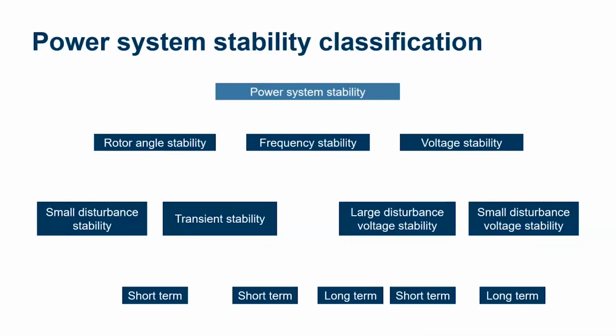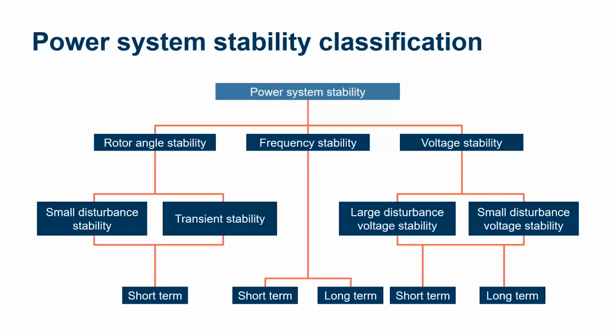So what does that mean? That means system integrity is preserved when the entire power system remains intact with no trippings of generators or loads or other electrical assets, except for those disconnected by isolation of the faulted elements or intentionally tripped to preserve the continuity of system operation. When we talk about power system stability, there are three main areas: rotor angle stability, frequency stability, and voltage stability.